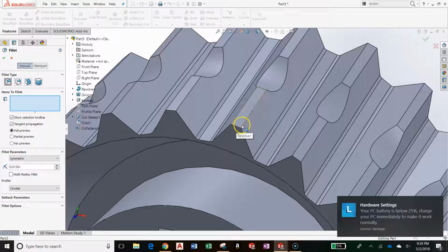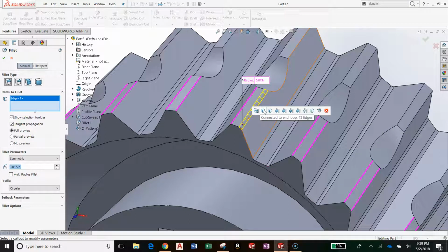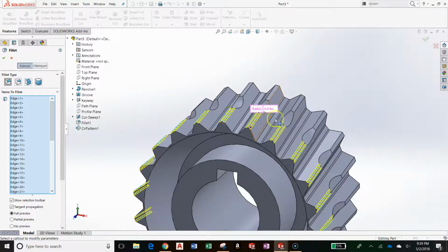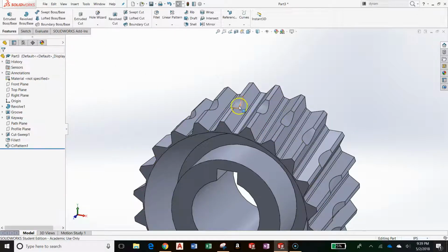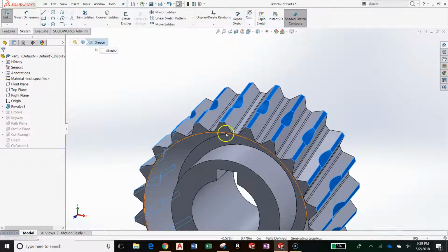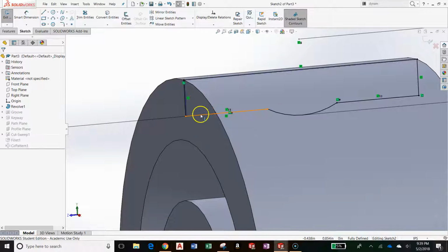Now, the autonomous feature can get quite a few of them, but it doesn't get them all. It would still end with me clicking on like 20 different edges independently, which sounds highly annoying, right? So instead of doing that, I decided to do this groove cut here. I decided to do this so that there's a completely separate feature that will contain the edges and the arc